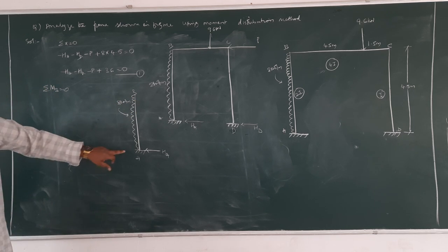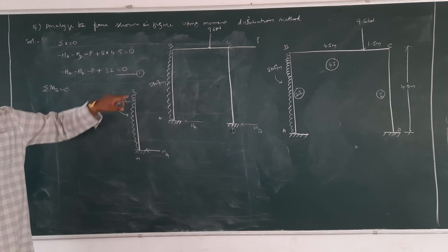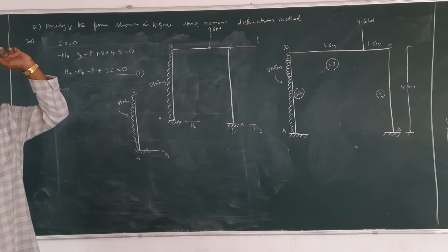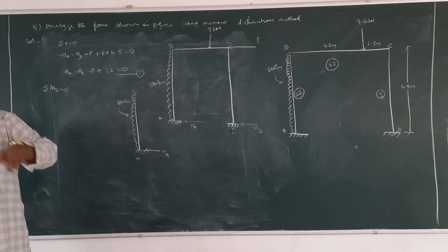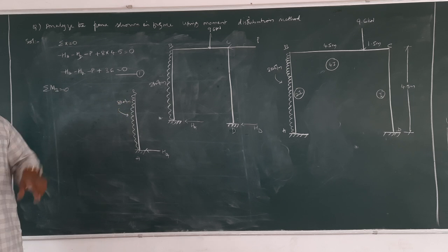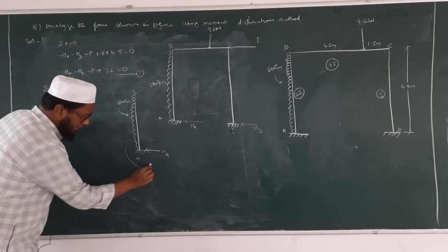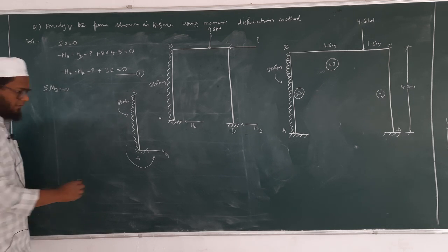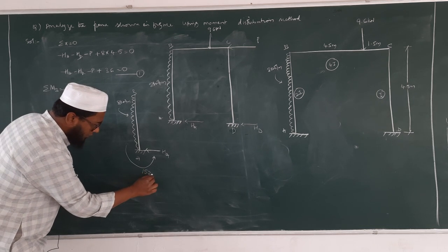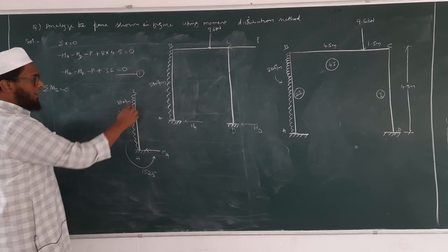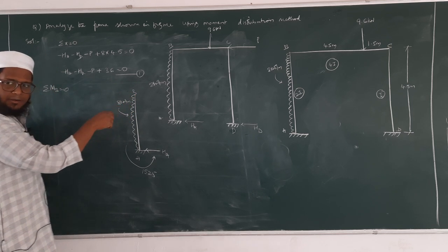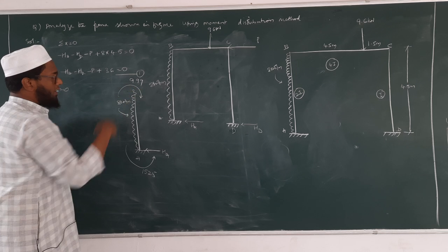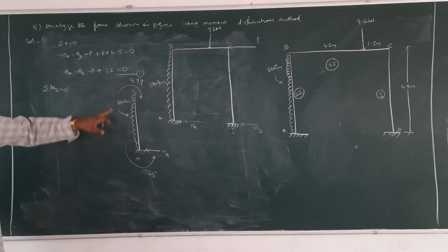Okay. And also if you are considering only span AB and we are calculating moment here, so we have final moments, isn't it? What are those final moments? MAB and MBA. This MBA is going in anti-clockwise direction. So that is 15.25 and this one is going in clockwise direction, right? 9.99. Okay, agree with this one?